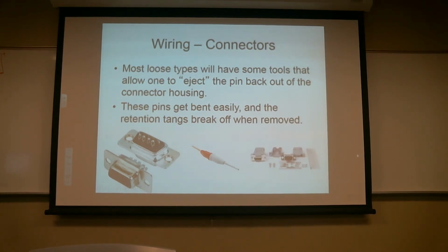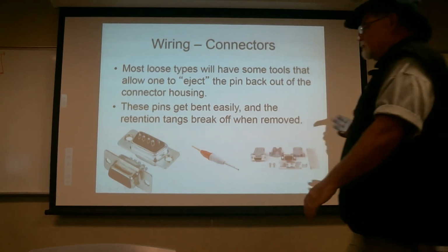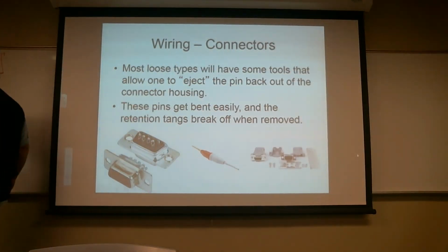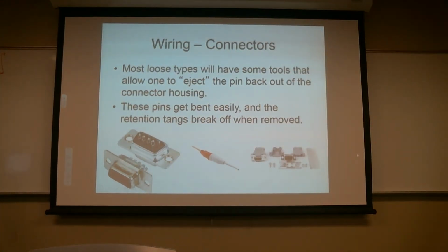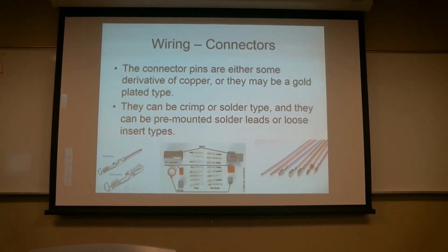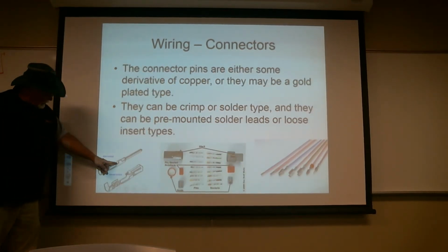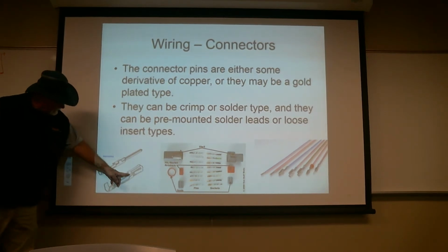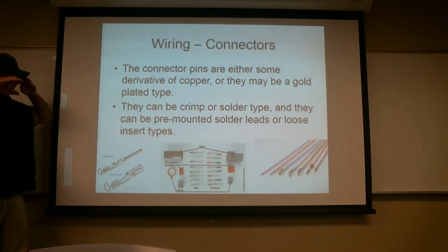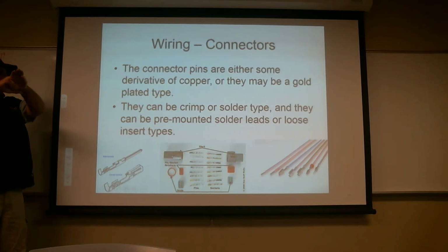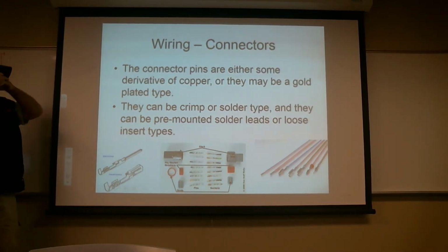And the way to get it to eject with the ejection tool is you come in from the back side of the housing and lift that tang up. In the previous page, and again, there's a bazillion different types of tang, you'll see here you've got a little tang that comes up. As that goes in the hole, there's a little latch that the tang then pops up and out of. So you have to come in from the other direction and gently nudge that down to get it to back out.